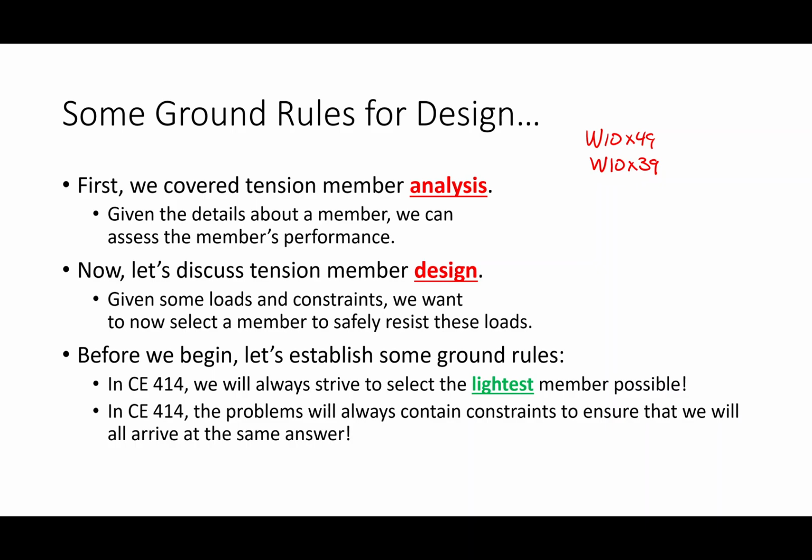And I'm doing that for the purposes of the class. Again, you probably aren't going to have those constraints in the real world, but some of those constraints aren't that unrealistic. For example, if I have to design a column, so there's a column right there in the wall. If I have to design a column to withstand those loads, the architect said the column's got to fit in that box. So you've got to pick a column that can fit in that box. You can't pick one that's like 24 inches wide, okay? So right there's a constraint from the architect. That's not unreasonable, okay? So the constraints that I'm putting on here are constraints that you would find in the real world. I might say, pick a member of this grade of steel. That's actually pretty common too, because most shapes are going to be available in typical grades. So again, we're going to try and keep the constraints as real as possible.